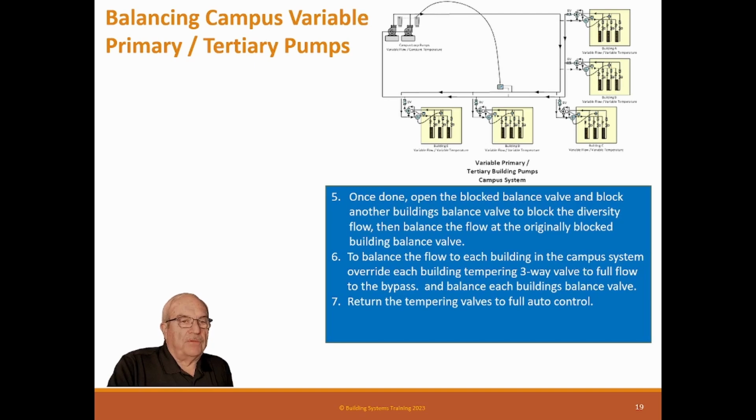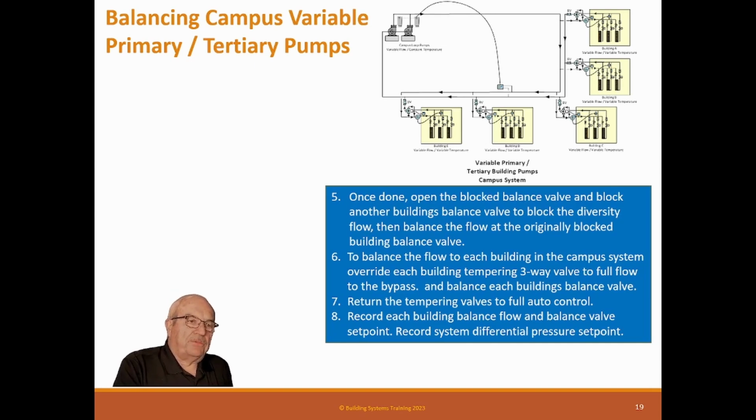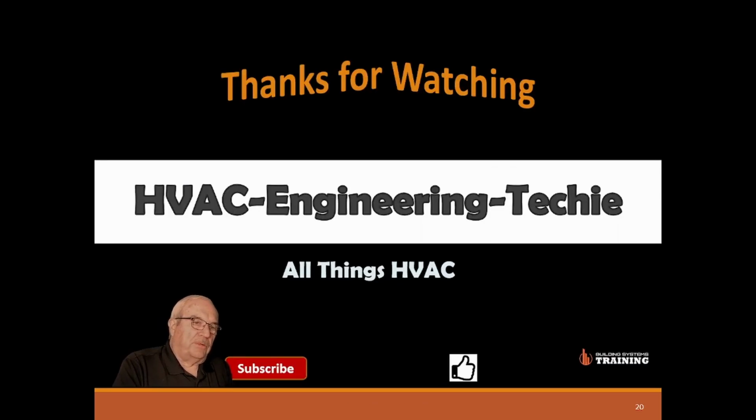Return the tempering valves to fully auto control, and of course the pump to full speed control. Record each building balance flow and balance valve set point. Record system differential pressure set point. So campus systems look big and scary, but really they're pretty simple.